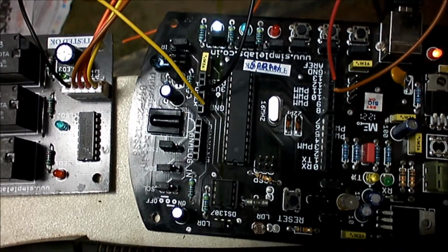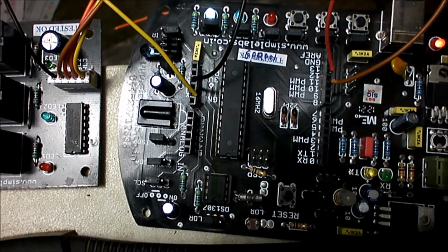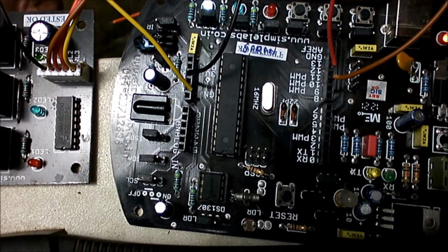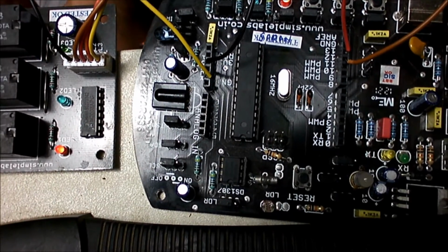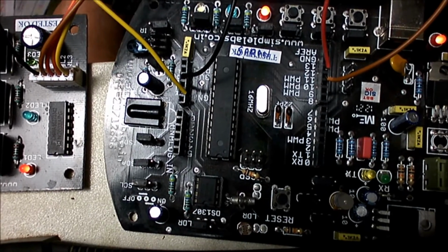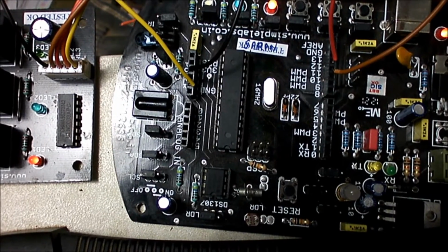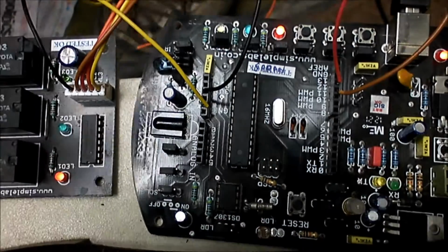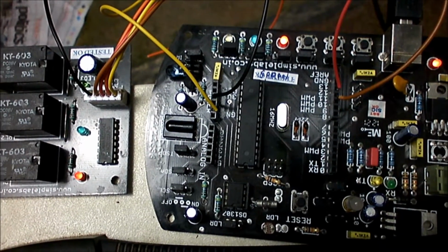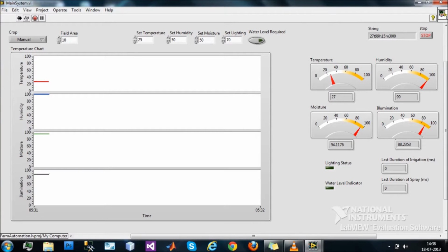The third level is the control level. The various outputs are controlled using a separate Arduino board. The outputs are controlled with the help of relay circuits. The outputs are dependent on fuzzy logic, which is obtained from the LabView coding to the Arduino board. Here, the fuzzy inputs are soil moisture level, relative humidity, and temperature, whereas the fuzzy outputs are the drip system and the sprayer system. Multiple field levels can be controlled using a centralized control level.